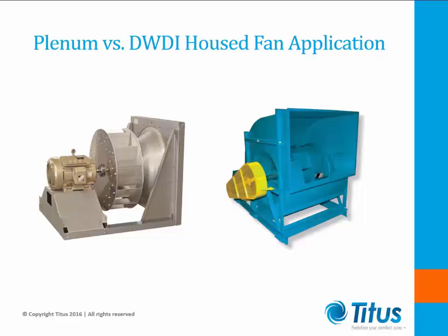Lastly, we'll take a look at the direct drive benefits. Specialty double-wide fans can be used in direct drive arrangements where the fan wheel is directly mounted onto the motor shaft, and most typically housed fans are driven by a belt and sheave system. Belt drive systems typically allow for 3 to 5% of efficiency loss and impose maintenance requirements not present in direct drive systems. Additionally, belts wear and give off debris in the form of belt dust. Many more discerning engineers apply direct drive plenum fans with VFDs for efficient variable volume duty and trouble-free maintenance.